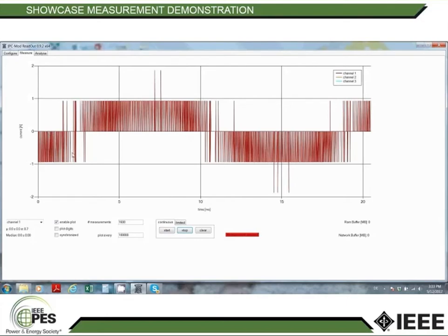This is because we switched to a sinc 1 filter, which basically goes through the iteration of integrating the signal only once, while the sinc 3 does that 3 times. So the sinc 1 is a little faster with getting you the result, but the resolution goes down significantly. Now, this shall be it from our little showcase right here. Now, we will go back to the presentation and have a closer look at a slide that shows a little bit more detail about what happens if you change the filter topologies.